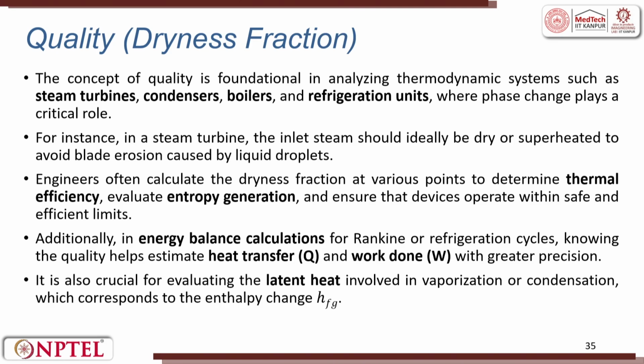So, the concept of quality is foundational in analyzing thermodynamic systems such as a steam turbine, condenser, boiler or refrigeration unit. For instance, in a steam turbine, the inlet steam should ideally be dry or superheated to avoid blade erosion caused by liquid droplets.